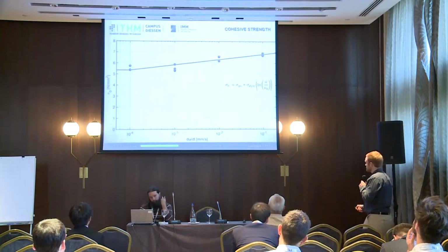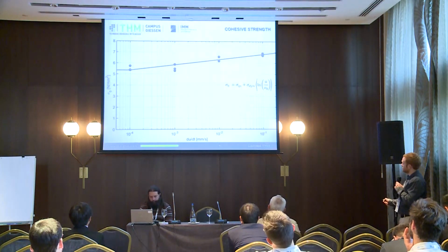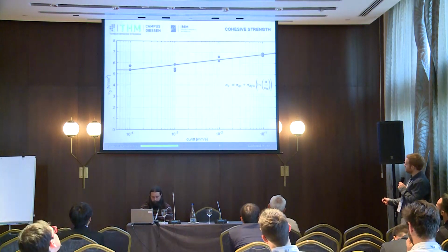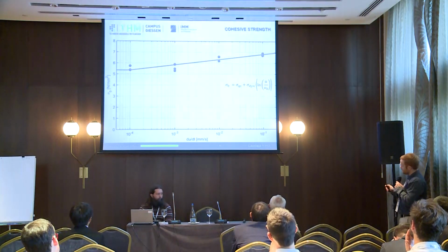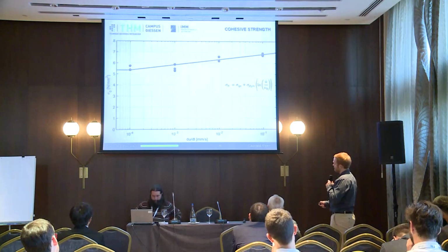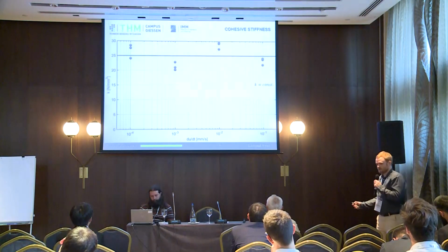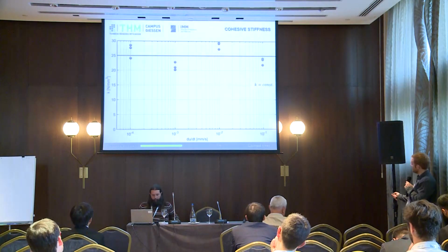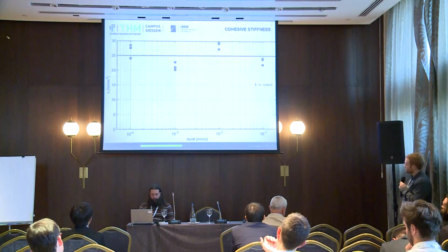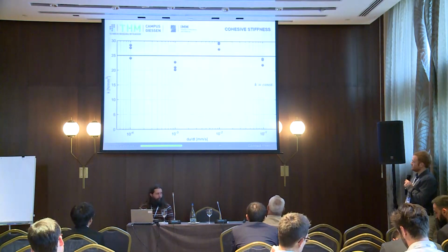And another parameter which is rate dependent was the cohesive strength. Another approach here, and again we have a lower plateau. This is a parameter giving you the slope of this curve here, and this is the quasi-static test speed or crack opening velocity. And as I said before, we've seen no dependence of stiffness on crack opening velocity, so we assumed here stiffness to be constant. We have large scatter, I think, but it was not possible here to create a convincing dependency.